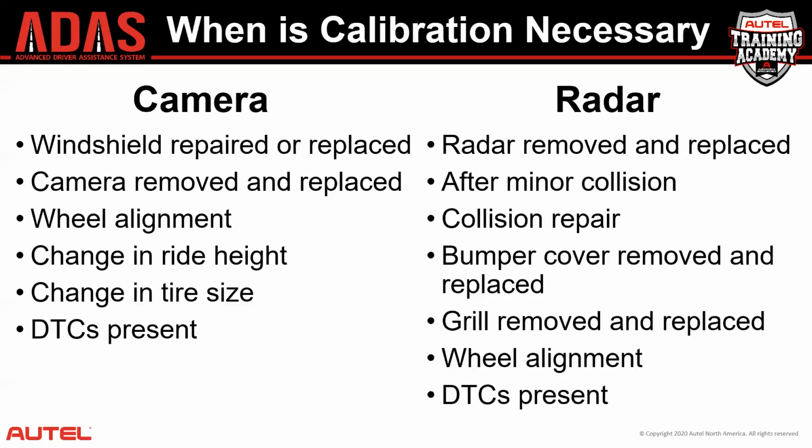Now, on the radar side, much of this is very similar, minor collisions. A bumper, minor fender bender, or just a bumper touch in a parking lot that requires a little bit of resurfacing and repainting would still require recalibration. If you're going to do any refinishing to a bumper, you're changing the type of paint or the thickness of paint. We need to teach that radar sensor about those changes.